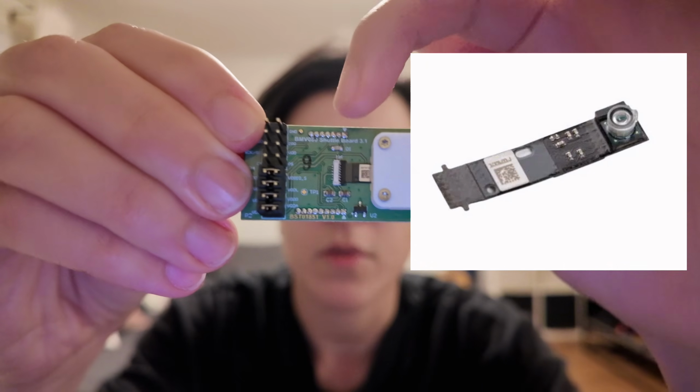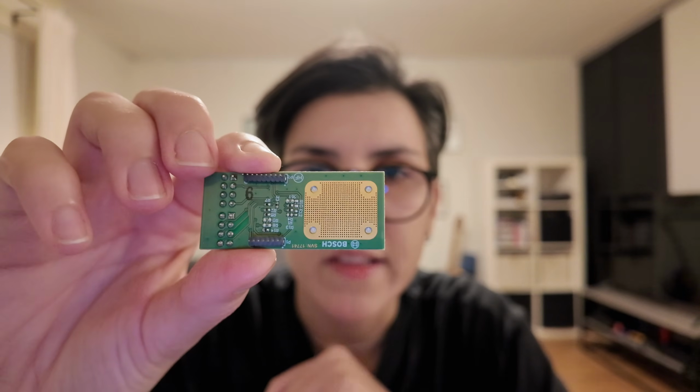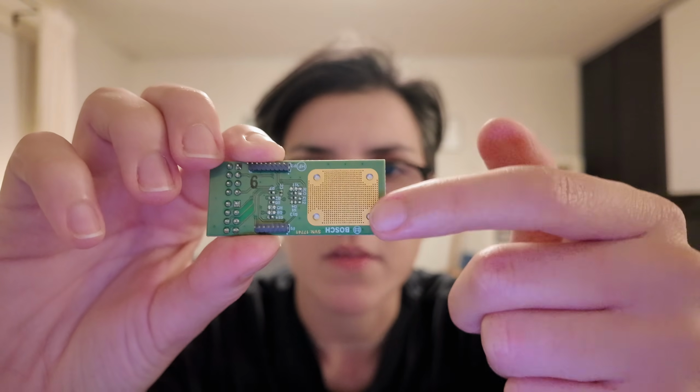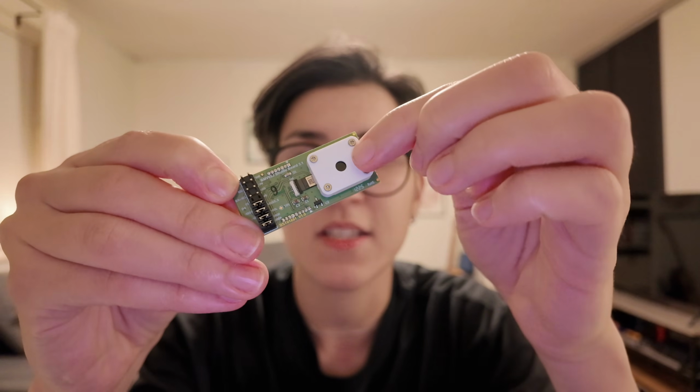So this sensor, which is the Bosch BMV080, is very special because it doesn't have a fan and is 400 times smaller than other traditional particulate matter sensors. But it also comes in a weird form factor. The sensor sits on a flexible PCB and you need a special connector to go with it, this one here, and then it needs a quite large heatsink. Here you can see a PCB heatsink, and it needs a lens to see the world through.